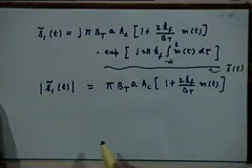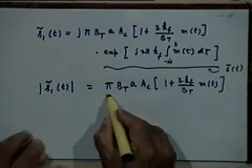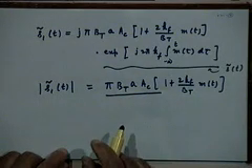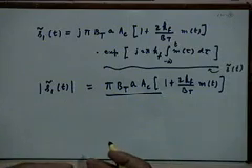Now, what can we do to take care of the DC component present here, which we did not want? As we know, the answer is to have a second slope circuit with somewhat different characteristics than the slope circuit we are using here, so as to balance this out. That is what we need to do. So, what can we do to balance it out? Let us look at that slope circuit again that we have considered.